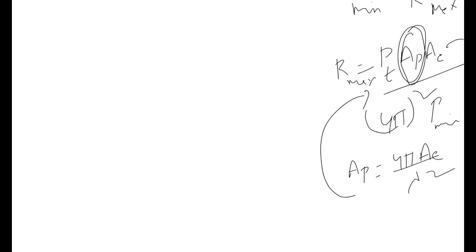Next what we have? Mixer. Two points are attached to the mixer. What are they? One is the local oscillator, another one is the low noise radio frequency amplifier. These two are connected to the mixer. From the mixer it is connected to the intermediate amplifier, then to the detector. I will enlarge the diagram. From the detector it goes to the video amplifier, and from the video amplifier to the display.